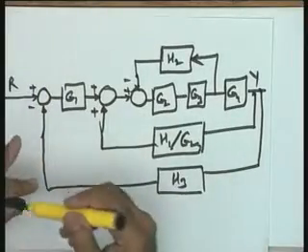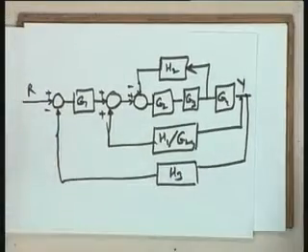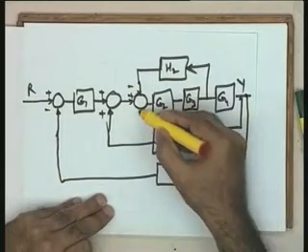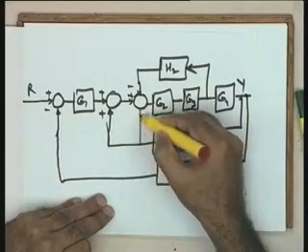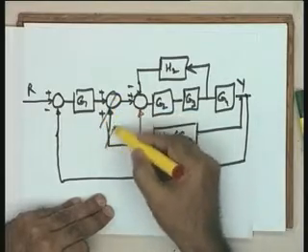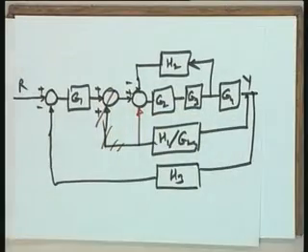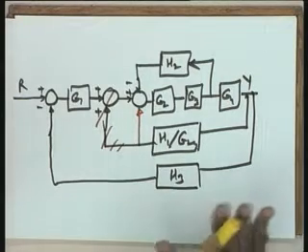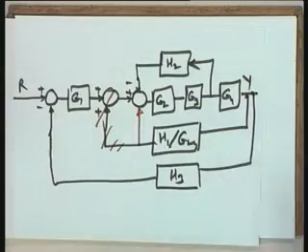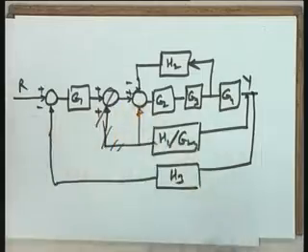Well, okay, there is absolutely no problem. I could have fed in. You see, his point it should be understood. There is absolutely no problem. As far as the block diagram is concerned, it is complete if I put it here and remove it here. Remove this point. The block diagram is valid, but the only thing I have done is I have put two summers so that your basic block diagram should be easily identified. That is all. Because putting two summers or one summer does not matter, because these are not the physical devices.